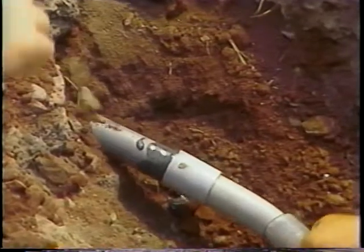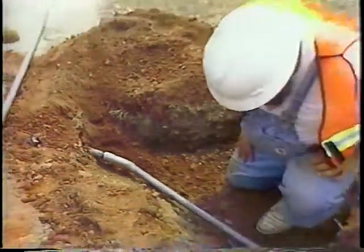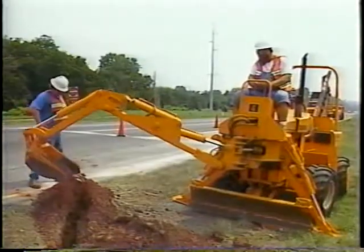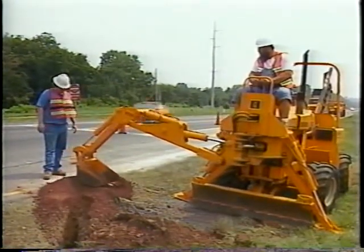Whether by itself or within a waterproof conduit, the cable should be placed in a trench at least 18 inches below the surface. Next, the trench should be backfilled with up to 6-inch layers. Then, use mechanical tampers to compact each layer to the density of the surrounding ground.